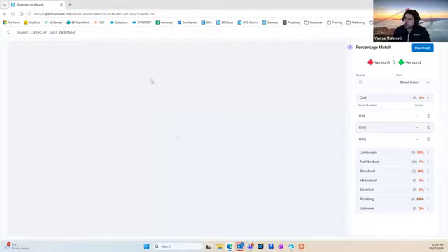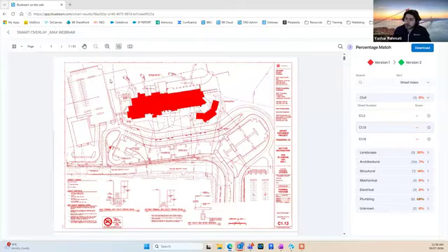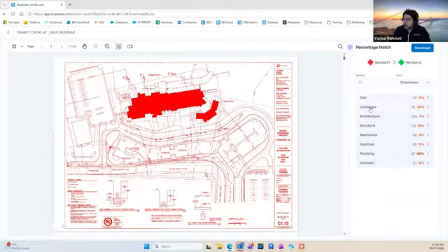Smart overlay. So this one, we can see it in here. And now from there, I've got my first version, I've got my second version overlaid on the corresponding pages. Also, it creates for me an interactive area in here with all the sets. For example, all my civil files are stored in here. All my landscaping pages are here. All the architectural pages are here. And if there are some missing pages in the new sets, obviously I don't get that there.